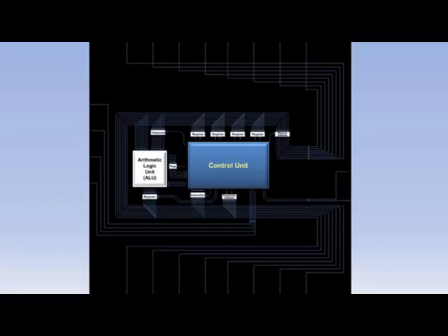out to the pins on the chip. On the right are the set RAM and enable RAM wires. On the top are the RAM address wires. On the bottom are the data wires that run to both RAM and the external devices. And on the left are the input-output control wires. So let's zoom back out.